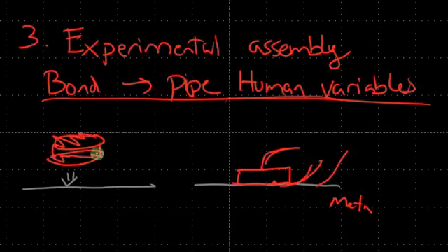They have to be electrically activated, and if there's actually epoxy here, there will be a reduction in the electric field across the PZT because of the drop in voltage over the epoxy, which is acting like a dielectric material of low dielectric constant, which will drop most of the voltage. So be careful about that. Pull out a sort of shim or something like that to get that electrical contact in, and make sure it's flat. So okay, what I was saying here.